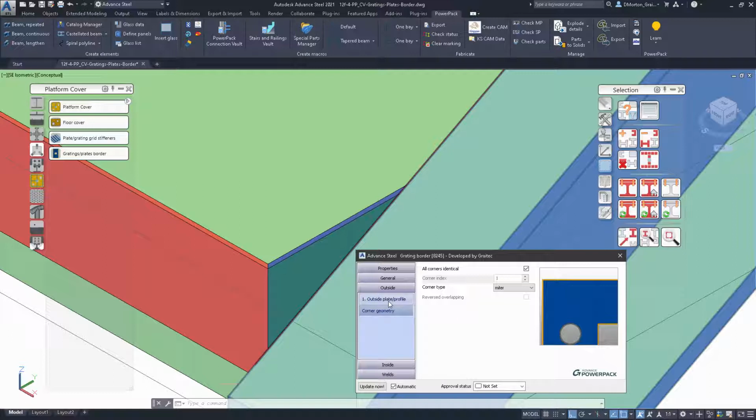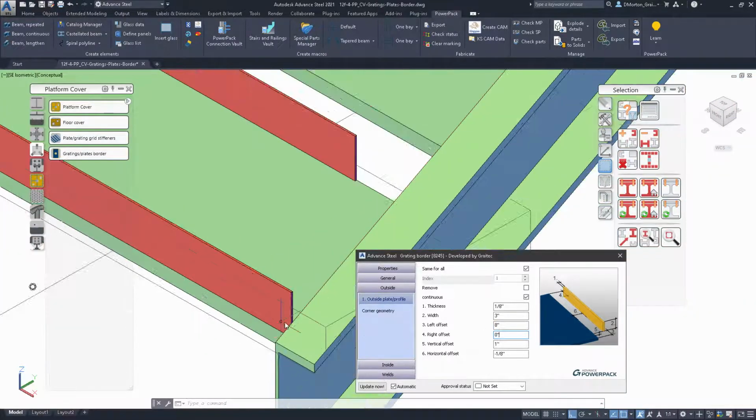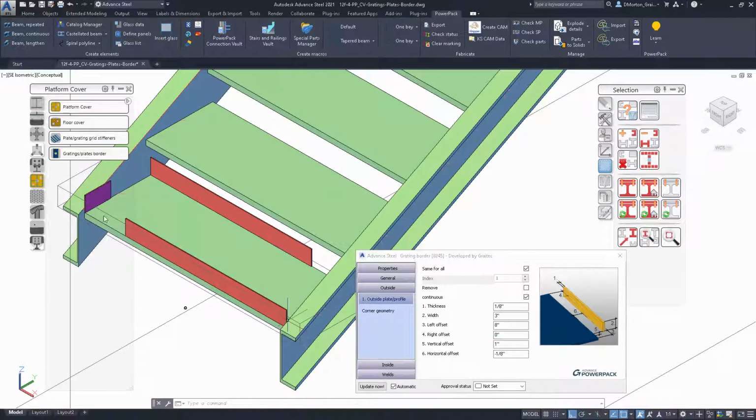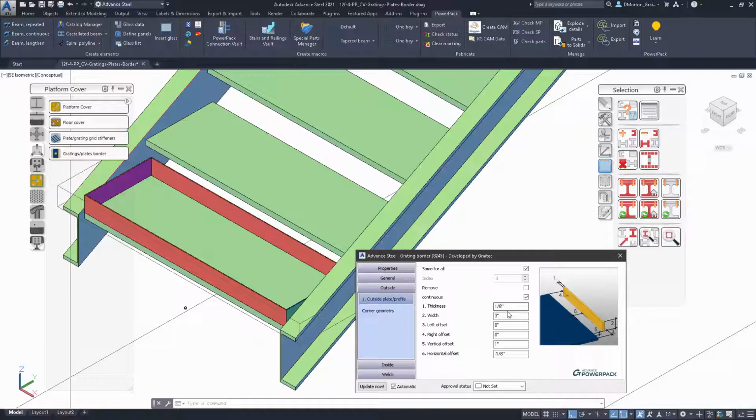Okay. If I say none, on the outside here, same for all, I can then do, for example, 8 inches. And you can see it's creating an 8-inch gap on all the different sides here. So it pulls the plate in, but I'm doing same for all by this distance. You need to remove the miter first, or this will not work. Okay. So if I put the miter back, the corners are mitered. When I come into here, if I put a value, nothing happens.